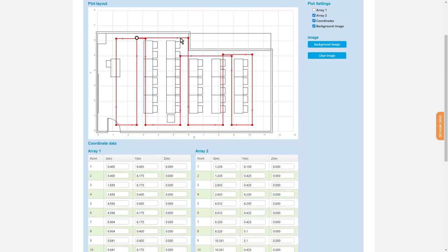and I'm going to add a new point so that I can start bringing the wire down and across. So I simply want to click the plus button here. That will add a new coordinate below. We put focus on the new coordinate so it's highlighted by default, and we insert that at the exact halfway point between the existing and the next coordinate.